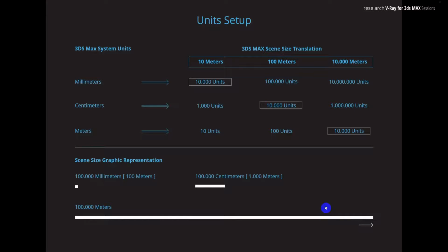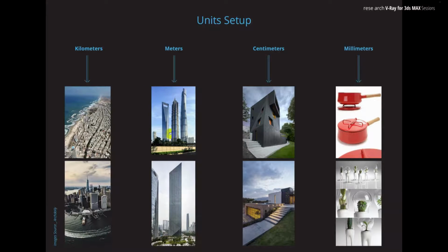So this is how you should be selecting your system units. And be absolutely 100% sure, even 200% sure, because it's really difficult to correct this later on in your file, because simply this is how everything is going to be calculated. So you can fix it, but it's actually an unpleasant process because you have to be saving your settings and all this. So it's really good to get rid of this at the beginning and not have troubles later on at all.